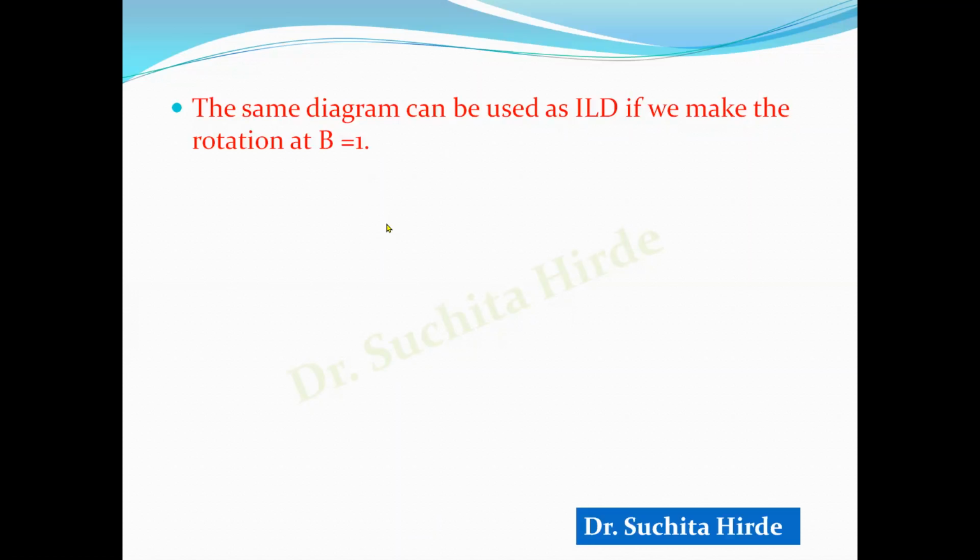And you know that we are solving these problems using the conjugate beam method, because in Muller Breslau principle we have to draw the deflected shape, and for drawing the deflected shape we are using the concept of the conjugate beam method.